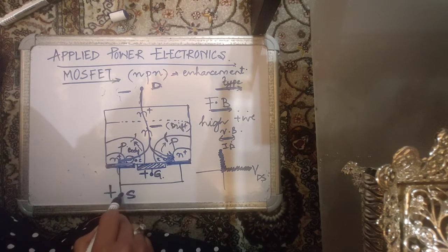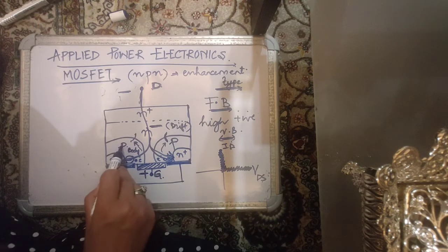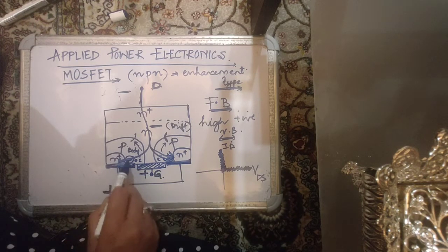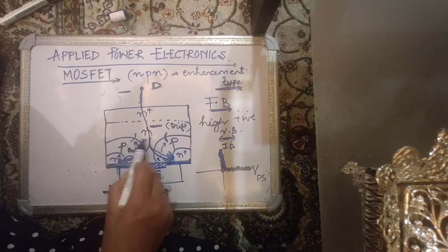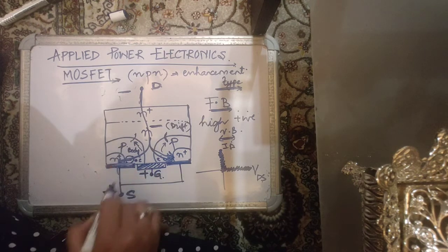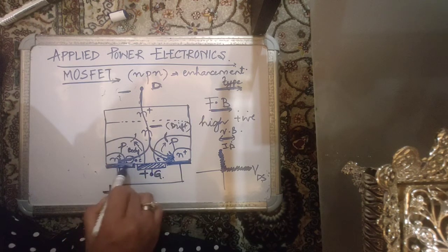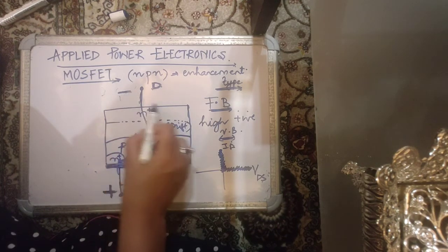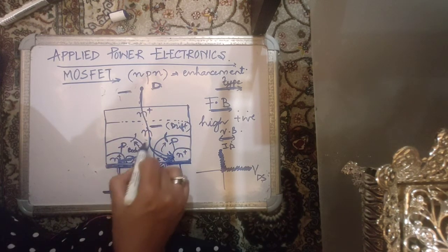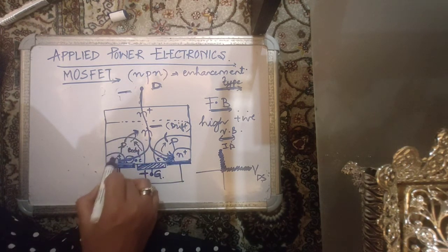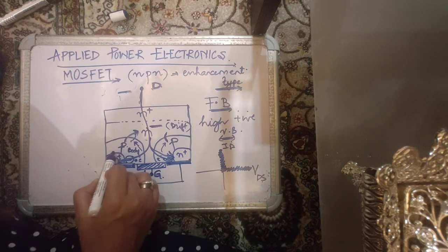It means that the source potential is brought to the p point, at the body point. And whenever I give a positive voltage at the source, it appears like this positive terminal is directly connected through the short to the body, to the p-type material, and the drain here is connected to the n-type material. So you're forward biasing this p-n junction, and you're basically bypassing the p-n junction which would have been reverse biased.